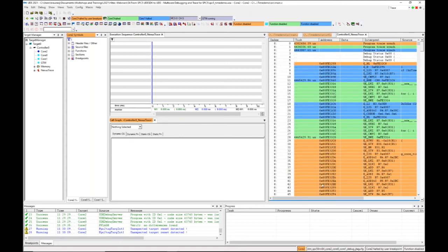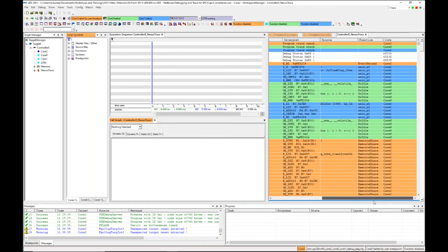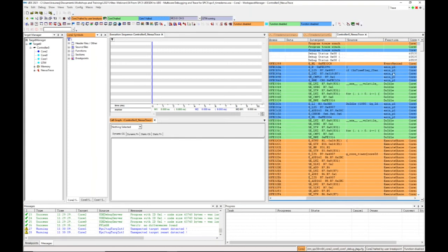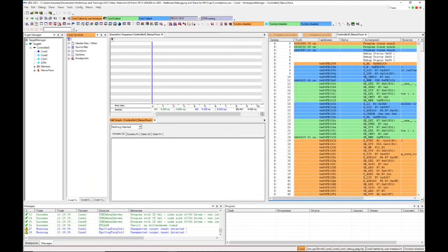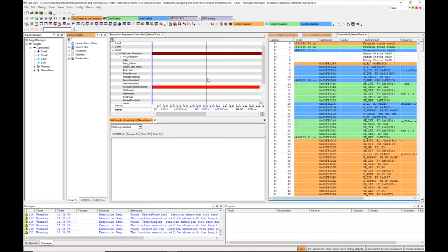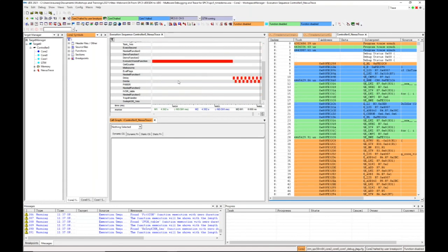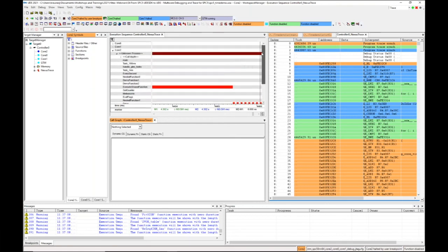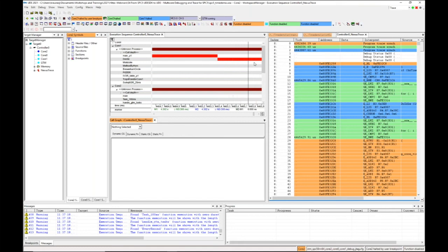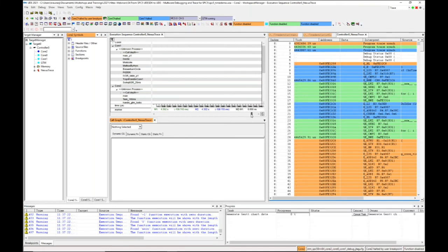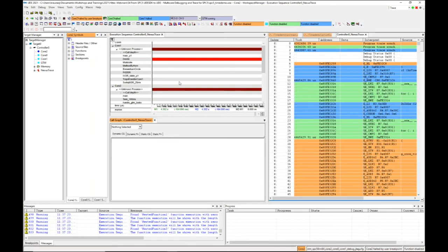And you see here in the trace window the executed instructions for all the cores, together with some timing information. But it looks very complicated, and there is another nice view available to get an idea about the runtime behavior of the system, the so-called execution sequence, where I can visualize the sequence of the executed functions. So I can open core 2, for example. Then I have some code that is executed, and some functions that are called from other functions. And I can also open the other cores, zoom in, and look for interesting points in the execution sequence.